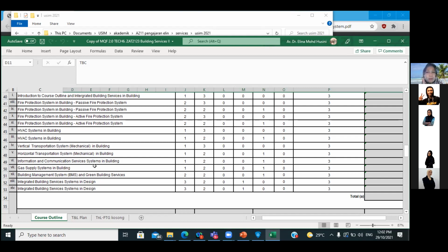It's because the tahfiz was exceeding the height of 12 meters. We understand that it's a 3-story building and they did have a secondary staircase at the back. But the owner, the maintenance, the manager of the building closed the secondary staircase and they put furniture and grilled the door. So when there was a fire at the main door, these 20 students could not evacuate.